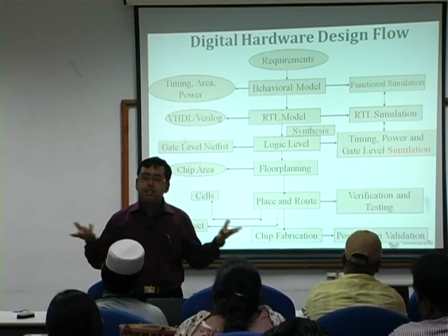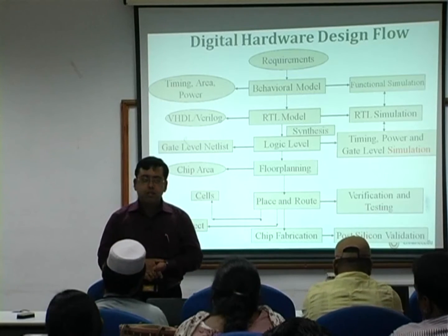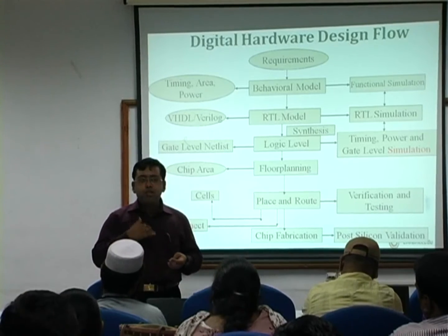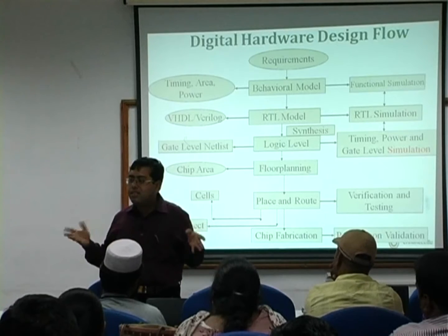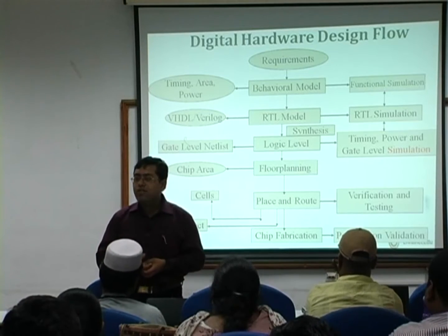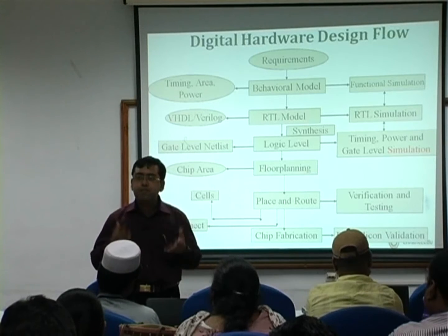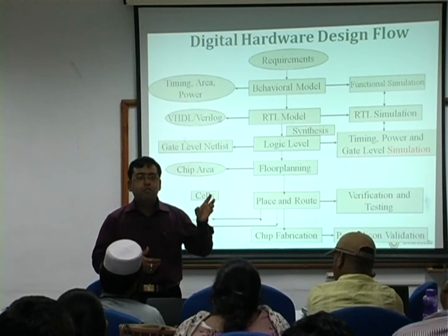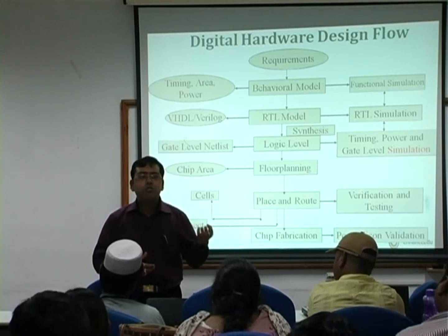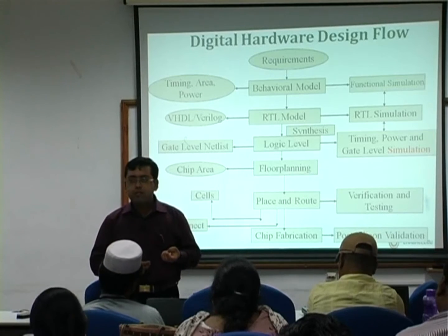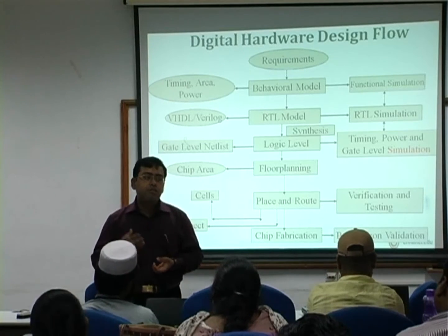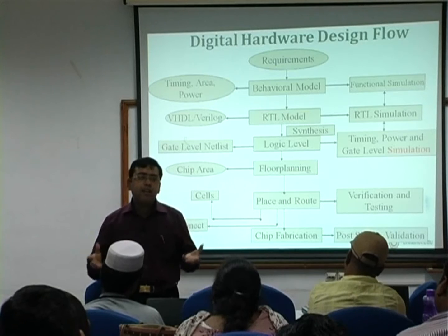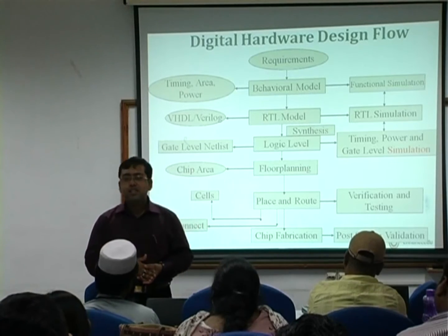So suppose you consider a circuit with some 40 inputs. If the circuit works on binary logic, then if you want to exhaustively test the circuit with all possible test cases, then there will be 2 to the power 40 cases of inputs. That is simply not possible. We have to test a chip with so many inputs with so little time, and therefore we have to try out some intelligent approaches by writing some algorithms by which we minimize the total number of test cases.